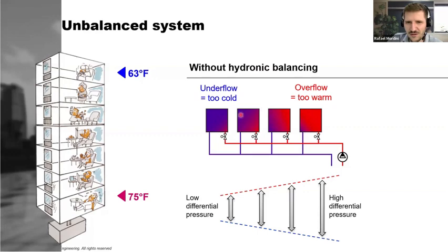Imagine all the circuits here are identical, same apartments, everything is equal. But why do we get different flow rates? Because the available pressure reaching each of them is not the same, because the water is losing pressure by friction on the internal walls of the pipe, on the supply pipe and also on the return.